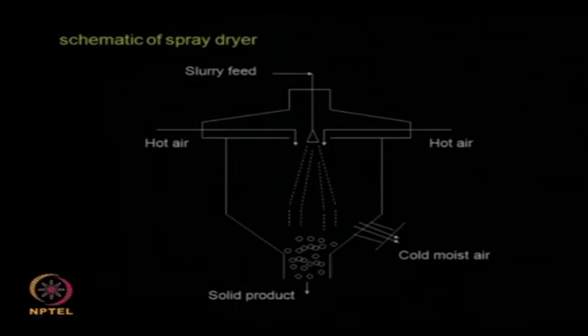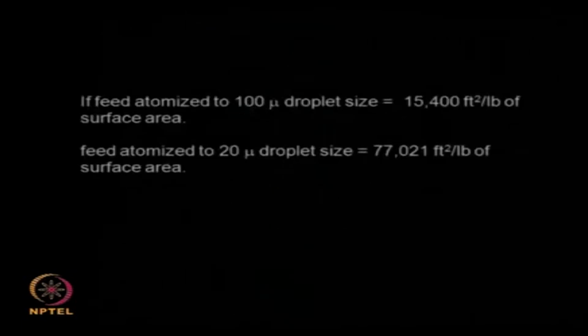So this is a very good technique and it is widely used in the food and flavoring industry. The beauty of it is, the finer the particles, the higher the surface area per unit volume. So with higher surface area per unit volume, the heat transfer is good, so drying takes place very fast, and also if you have this as a product, the solubility also increases because it has a very high surface area to volume.